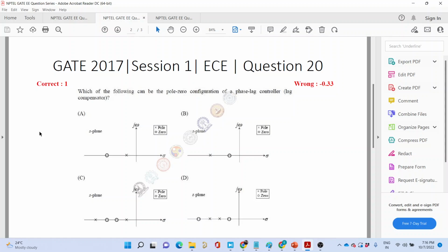So it is some constant a e to the power minus t plus b e to the power minus 2t, right? Yes, sir, exactly. So what are the two time constants? One time constant is 1, another time constant is 1 by 2. How do you get the time constant? It is e to the power minus t divided by tau, where tau is the time constant. So one is unity, other is half. So the one which has a lower time constant will decay down much faster as compared to the one which has a higher time constant, right?